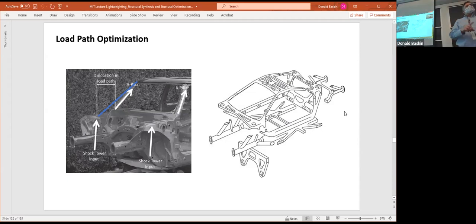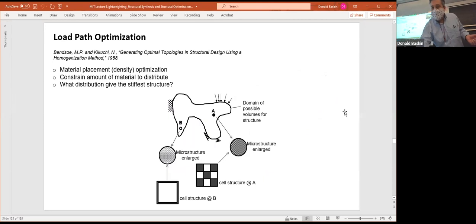So this is the geometrical part of this, right? We talked about materials. We talked about how you use computational materials engineering methods, for example, to develop materials that have a high strength to density or high stiffness to density ratio. This is now the geometrical part of this. How do you design the geometry of a part so you have the highest chance of a good structural efficiency? So the load path through a given structure, or say the place where a structure can live, and maybe has complicated boundary conditions, is not always that straightforward to figure out, right? When we have the 2 opposing forces, that's pretty easy. You just put a beam in between.